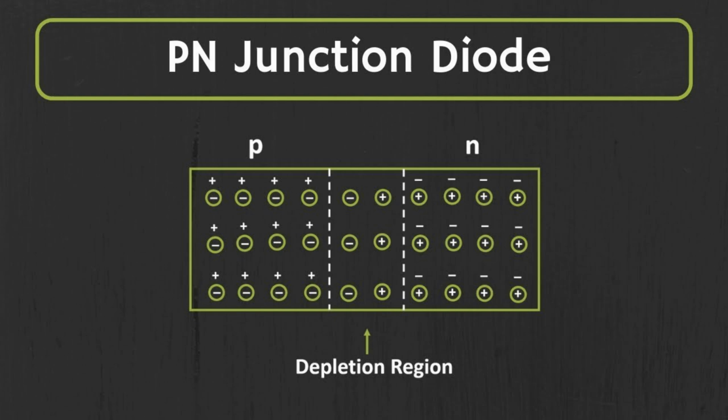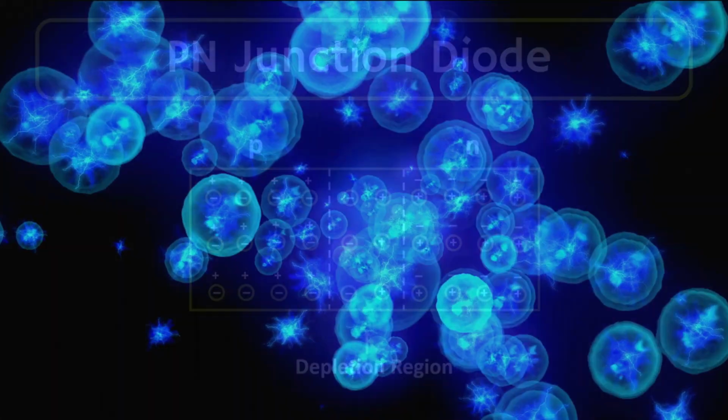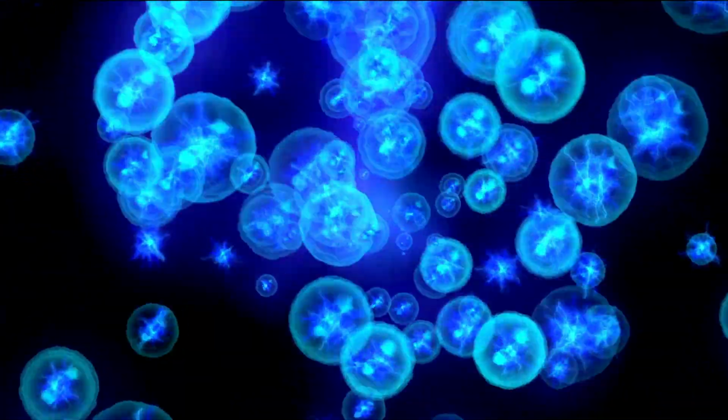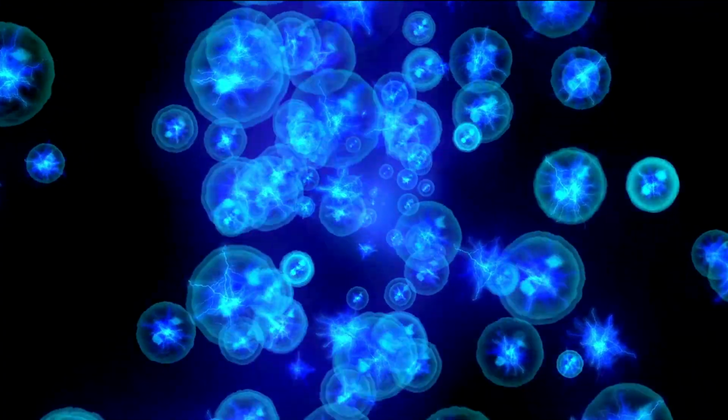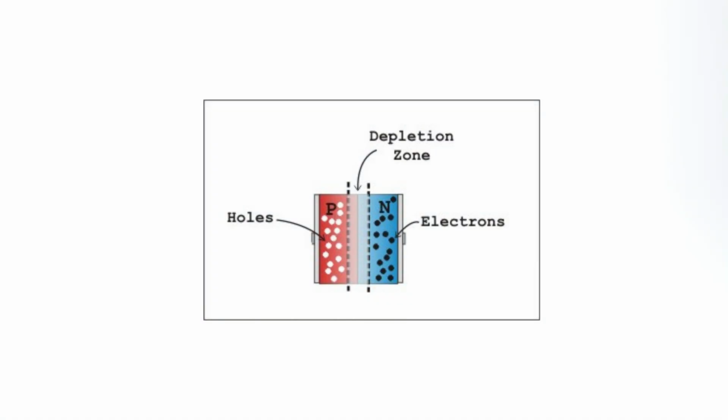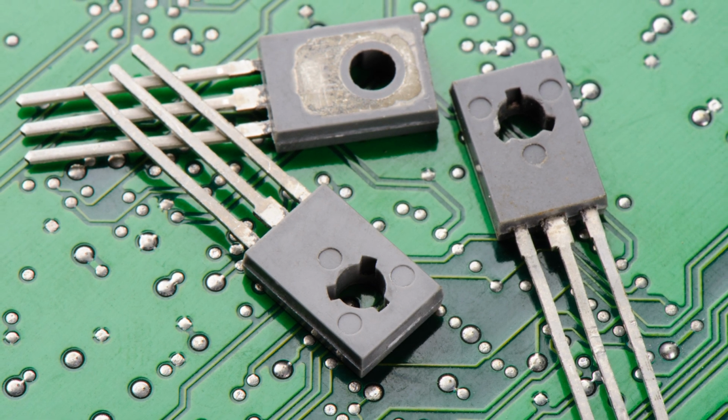A diode allows current to flow in one direction, from the P-type anode to the N-type cathode, but not in the reverse direction. When voltage is applied to the diode in the forward direction, the electrons and holes move towards the junction, recombine, and allow the current to pass through. In the reverse direction, the electrons and holes move away from the junction, creating a depletion zone, thus blocking the current. Using these principles, we've been able to build more complex semiconductor devices.